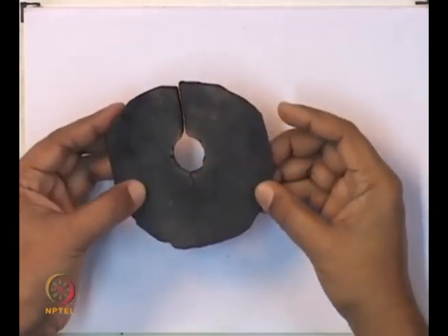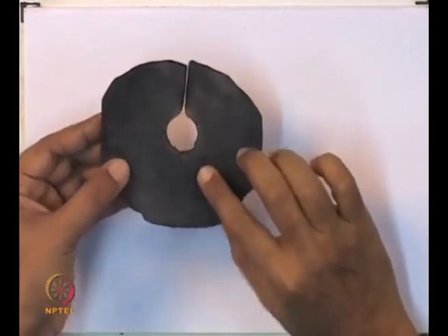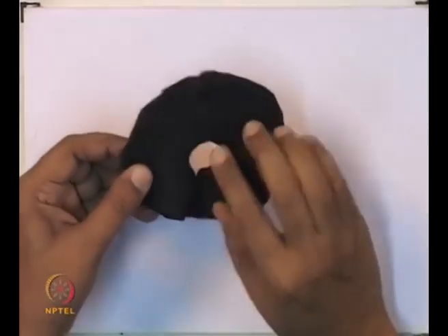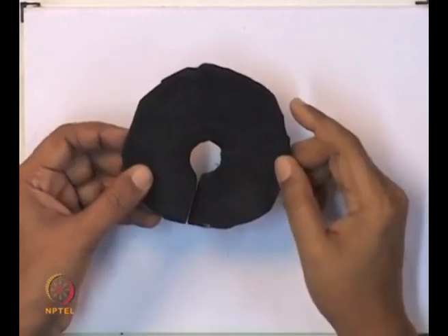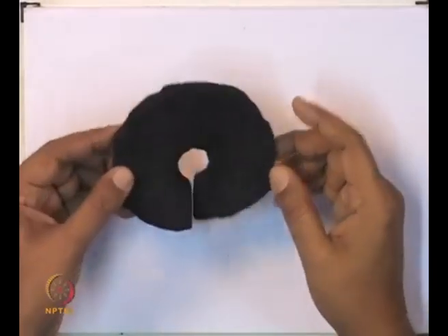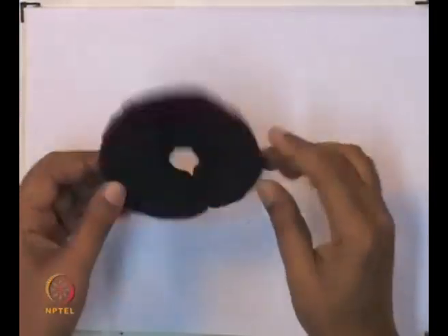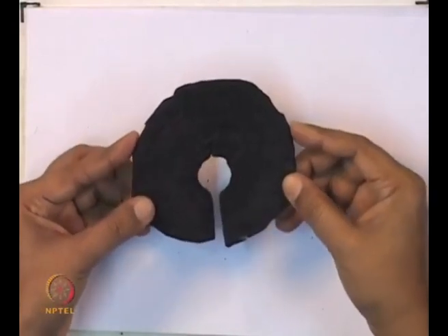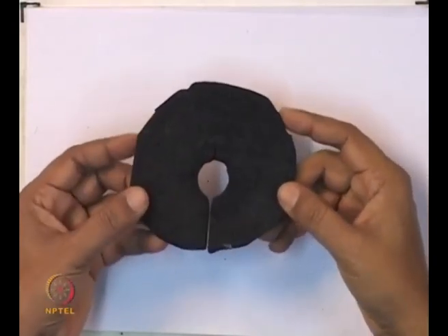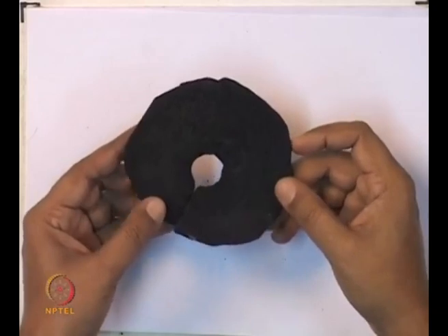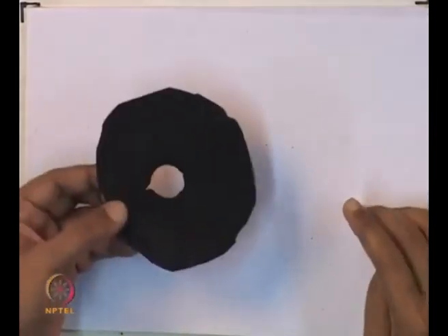On the back side it would look like this. This is what is exposed to the atmosphere, while all these structures see the cryogenic temperature. Alright. You can see some small powders falling when I rub my hand over this. So, this is not a very reliable kind of solution, but it is a very cheap solution which is available in the market and can be used for refrigeration purposes as well as for cryogenic pipelines.